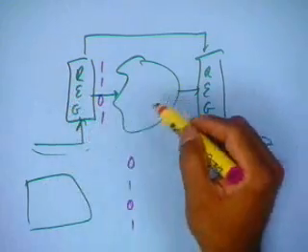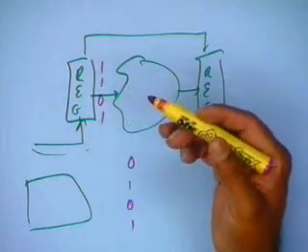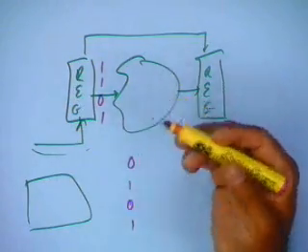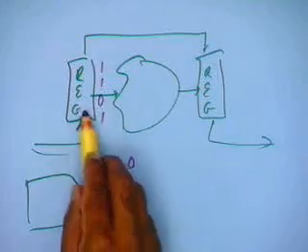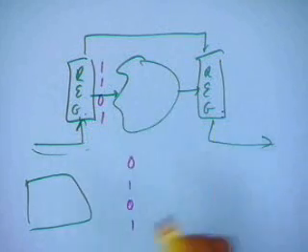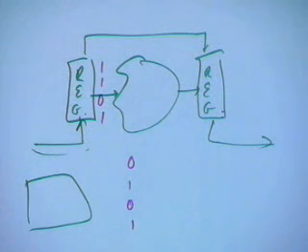So, after applying the test vectors, I am not actually running the circuit at full speed, I am slowing it down considerably. Of course, in this particular process you may be applying at maybe 20 megahertz, but a lot of these correlation effects come because when the numbers are changing, the faults also appear. See, almost all our test patterns are done with static faults. And we only talked of stuck-at faults, stuck-at 0 and stuck-at 1. We didn't even consider bridging faults. Of course, there could also be dynamic faults.